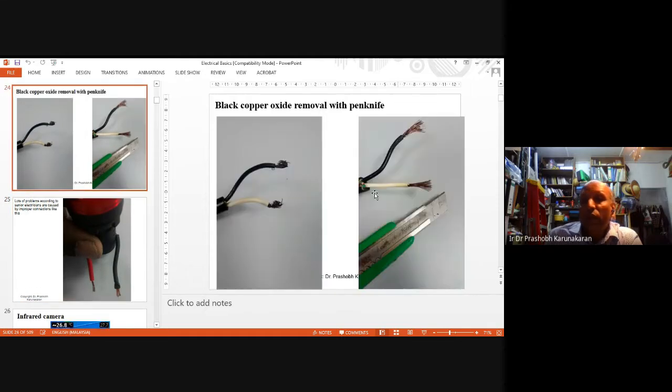You see, black wire is another issue. This one is in Unimas. This motor, for 4 or 5 years, it could not run. I went there, I just used a pen knife to scrape it, and it worked, because at the time I didn't have a file. My favorite thing is actually a file, so you must use a file to file off the copper. Sandpaper is one way, but I found that if you sandpaper with your finger, you tend to sandpaper your finger also. This one you can control a bit. So this is very important for you.